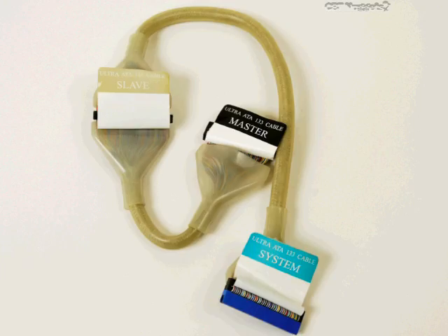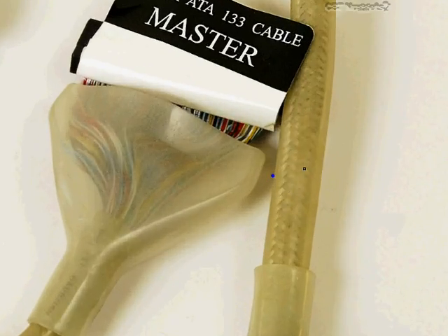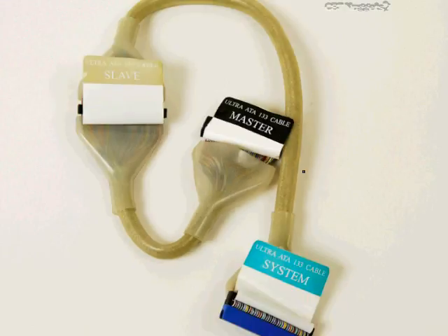Now, the cable I was talking about, we show here by way of example. This is a round cable, although most of them are probably going to be flat ribbon cables, which have a tendency to block airflow and are difficult to work with. That's why some manufacturers came up with a round design here, which they have also given additional shielding. If I zoom in here, I think you can see that there's a braided shielding that goes around it, which helps to mitigate the crosstalk that the 80-wire design is meant to help with.